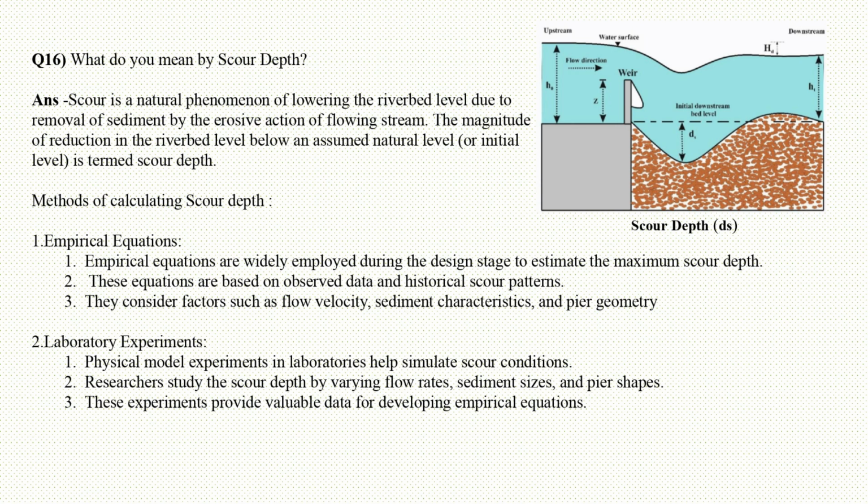2. Laboratory experiments. Physical model experiments in laboratories help simulate scour conditions. Researchers study the scour depth by varying flow rates, sediment sizes, and pier shapes. These experiments provide valuable data for developing empirical equations.